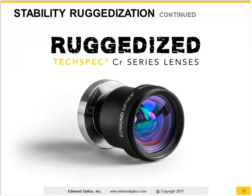Or long-term, as those optics do move around in systems, this can create problems with not just the beam pointing and the accuracy of the system, but as those optics slide back and forth, even though it's only a little bit, you eventually can wear the optics down and create more vibration issues, dust particles inside from the glass, other problems like that that can actually degrade the imaging system and the long-term quality of the image that's being obtained.